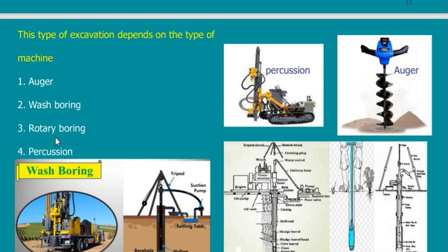or wash boring. Wash boring is something you have to imagine first. You remember in the war of 6th of October, they managed to penetrate the Bar-Lev wall using cannons of water. What is cannons of water? Just a water jet, pushing the soil, so it takes the soil and brings it back while coming back.